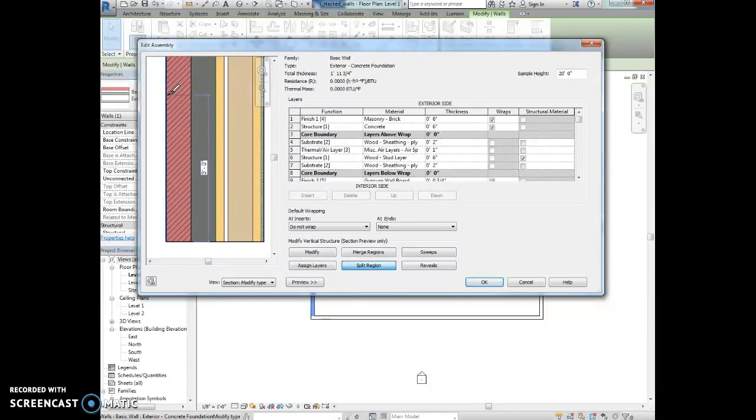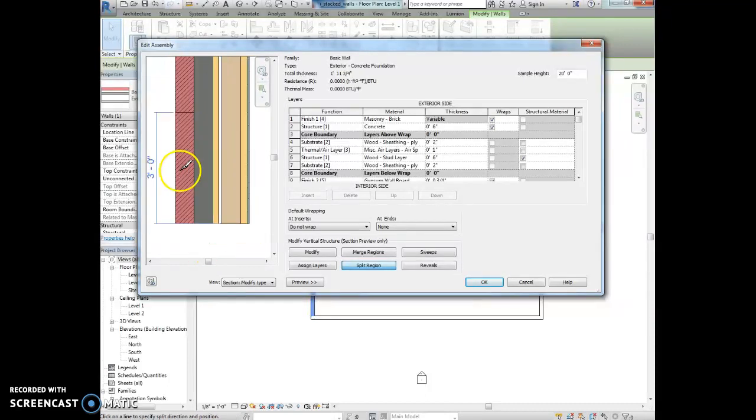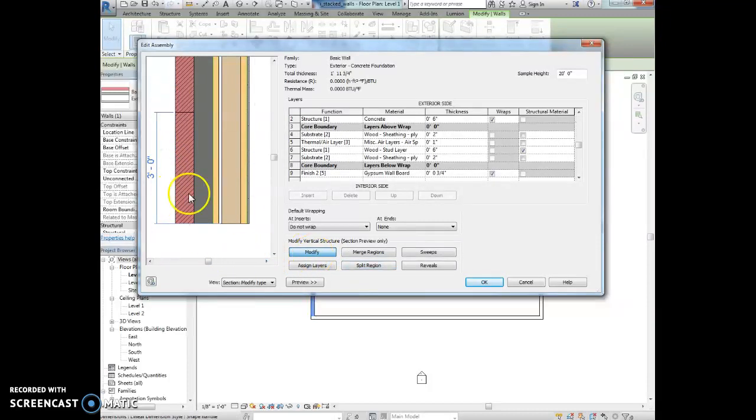And it didn't split it because it didn't show a line. So I'm going to try that again and click 3 feet. Okay, so now you should see there's a line here. And if I zoom out, it moved that line. It's at 3 feet. All right, make sure, again, you don't hit escape or it will cancel out of the whole thing. So now what I want to do is I want to select modify, and I want to